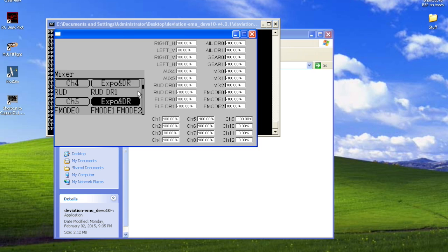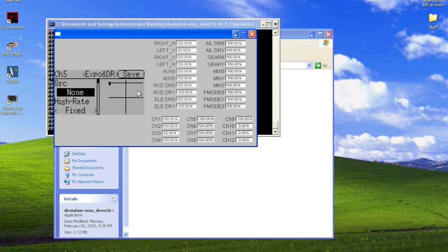You can get the full setup of your models here, I think, with this kind of understanding, and then from there you can experiment even further. But I think using the dual rate Expo that we looked at, and then when you're using things like the mix channels, you're going to use dual rate Expo, but you actually are going to make it a fixed value at each of the trigger points versus having an actual curve.